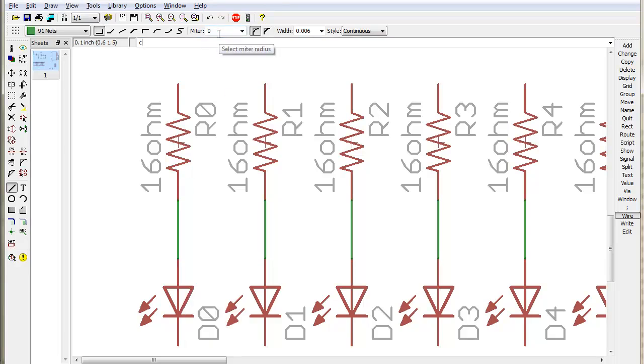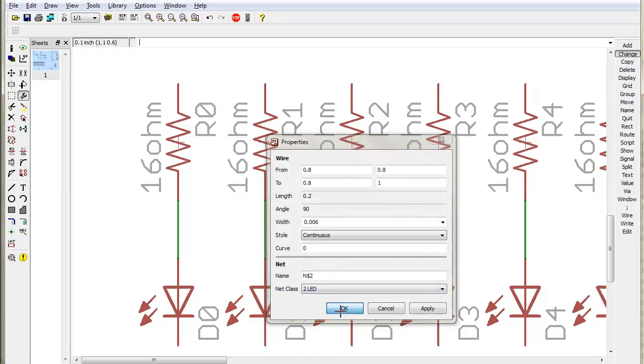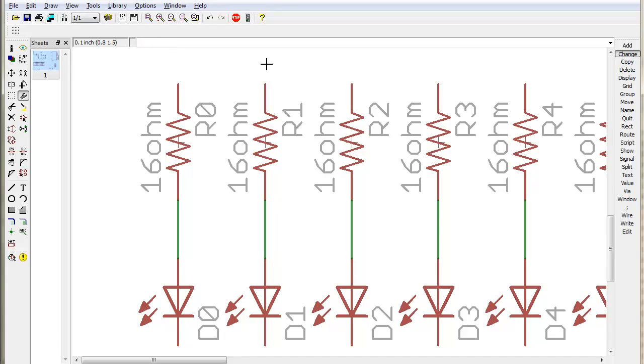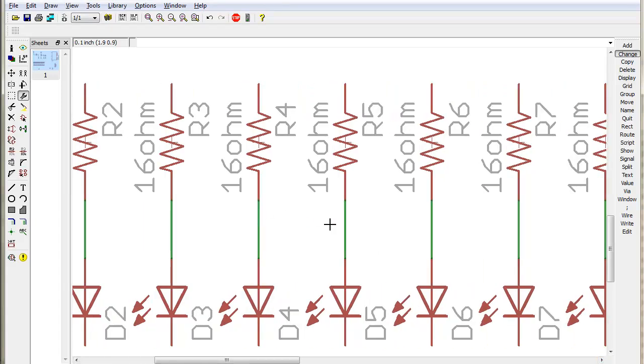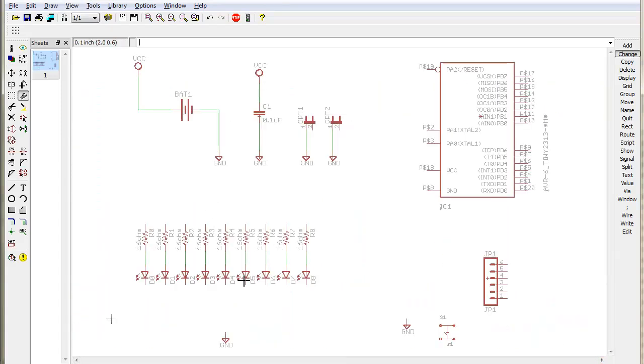The other way to do it is simply to do change class and then the class index, which is, as we can see, the wrong one. So that's number 2 we want to change it to. Change class 2, 2, and the green light flickers. 2, 2, 2, and just clicking on them, they're all changing. So those ones are on 20 mil, and that will come in later when we're actually routing out the board.